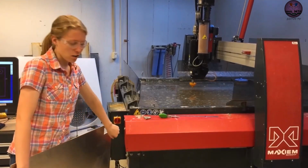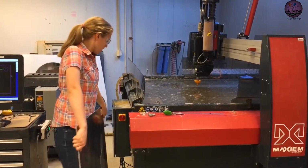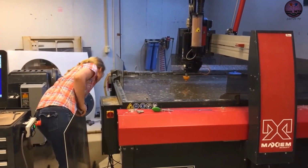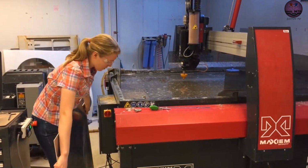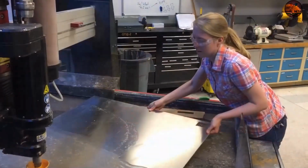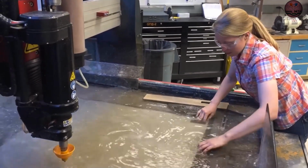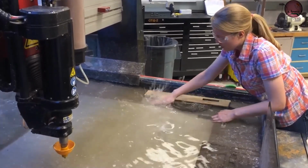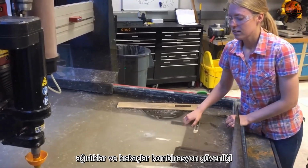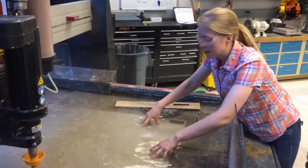So next, we need to load our cutting piece into the water jet. To do that, I will pull down this shield, lift it out, take my piece, and set it into the tank on top of it. So set it in there, and I will line it up with this L-shaped piece here. Next, I need to use weights and clamps or any combination in order to secure it.